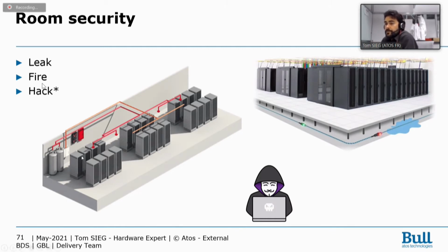Fire alarm. So fire alarm is the first point. The second point is, if you have a fire in your data center room, you have to put it out quickly and without damaging your already expensive material. The best system, of course, is gas, some argon gas or something like this, to cut the oxygen in the room. So people inside the room have to leave as quickly as possible, of course, but your fire will be down really quickly and your equipment will not be damaged.